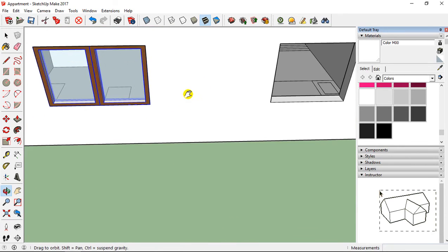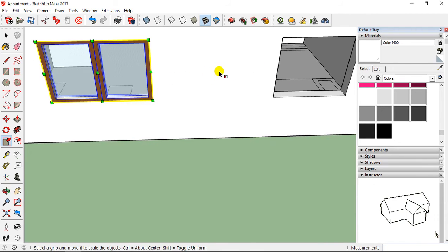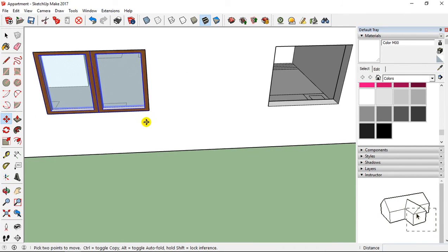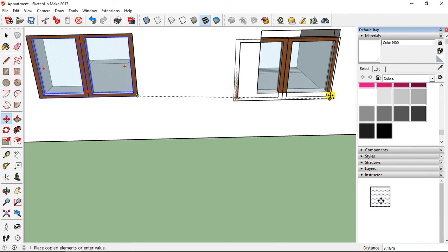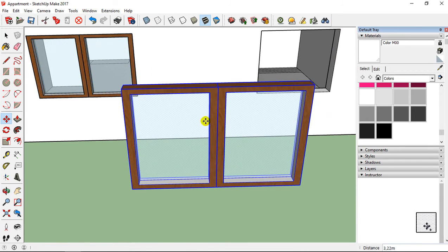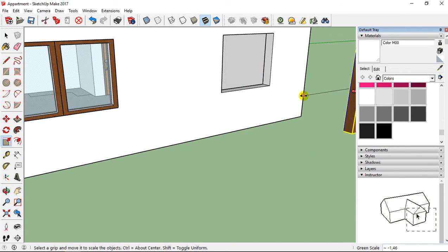Then I'm going to duplicate this shape to incorporate also on the right. It's not exactly the same size, so I need to scale after. So I take Move tool, I select an endpoint, I click on Control on the keyboard, and I duplicate like this. And for example, I can place, first I can place here, then Scale tool, and I can reduce just the size like this.